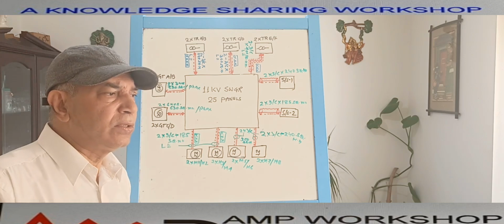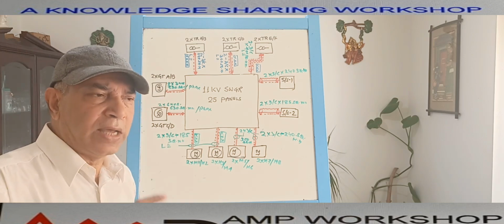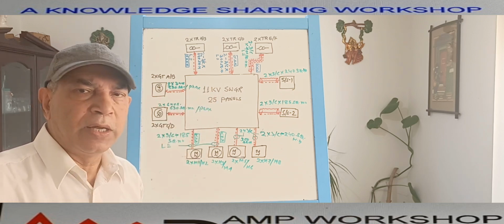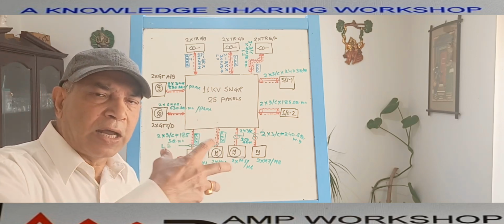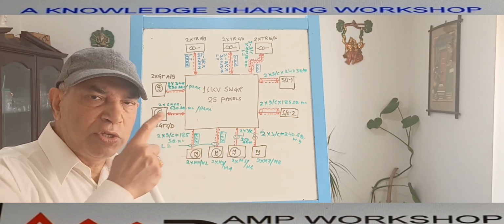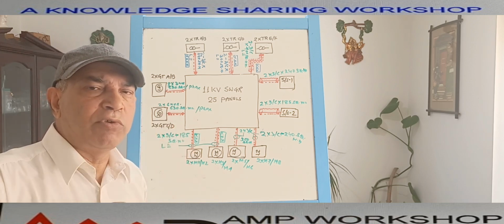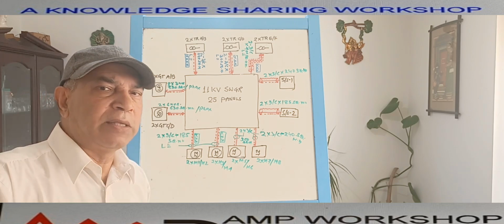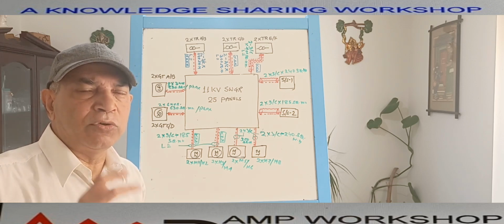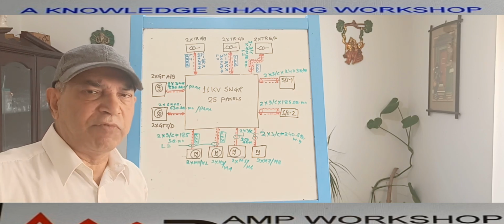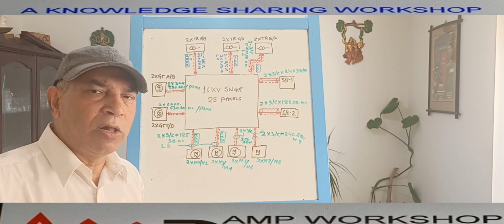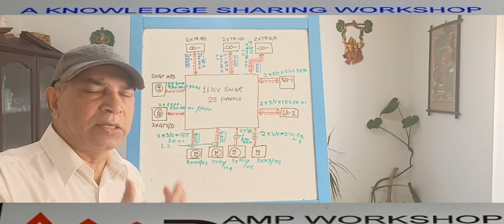In addition to this, all the power cables originate from the various field equipment and ultimately all terminate at the heart of the plant, that is the switch gear. So from the cable block diagram, we can immediately make out how many cables are coming to the switch gear and what cable entry provision we need. All the field cables coming from the various equipment, whether power cable or control cable, ultimately come to the heart of the plant, that is the switch gear.